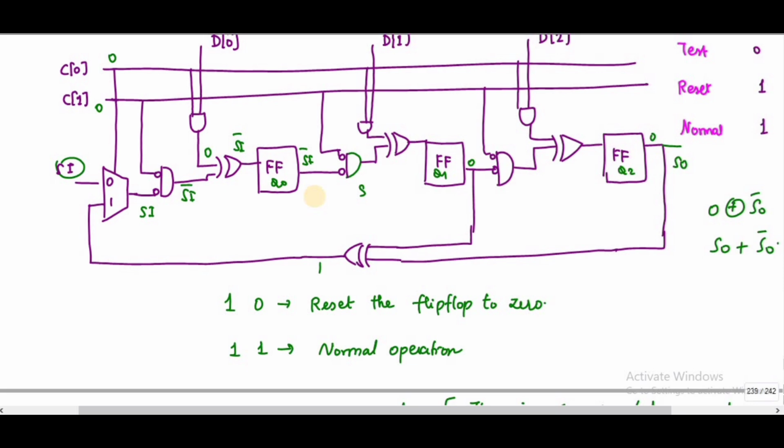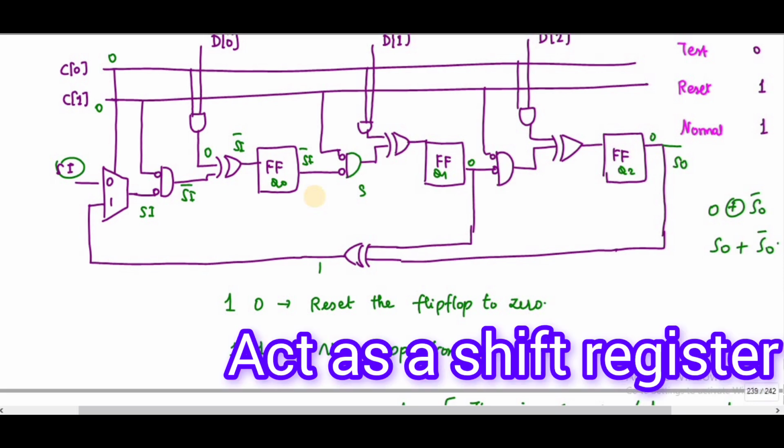So next, you can see since both registers are placed in the test mode, in order to produce this pseudo random input and calculate the syndrome, finally the syndrome is shifted out to the scan chain. Okay, so first it will reset the flip flop, then it will go to the test mode, then it will go to the scan mode. Okay, so if I want to perform the normal operation, I will have to select it as 1 1.